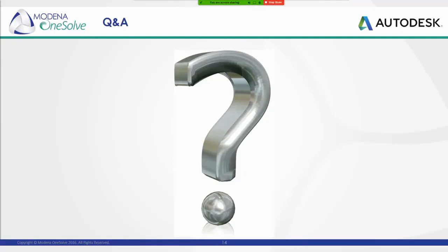Okay, so Pumlani has another great question. Could iLogic automate having to put in design limitations, modifying an existing frame to suit design requirements? Yes, that is exactly what it can do. It's rule-based design. So you define the controls of your model first, and as we spoke about, this is done in the earlier stages of Inventor at the front end with parametric design. Then after that, you apply iLogic for rule-based design, and that allows the model to maintain its engineering data and specifications. So anyone that comes to the form can't make a design that deviates from the engineering expectations that you set up.